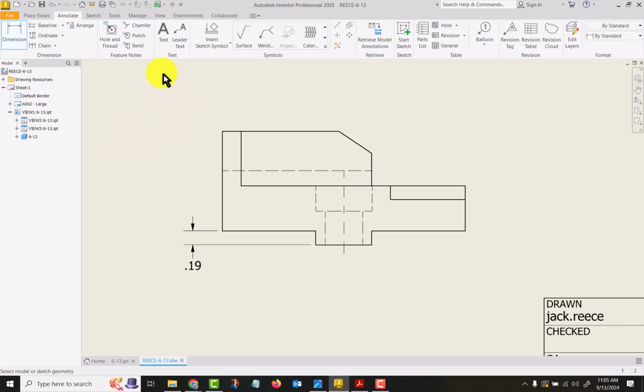And so now I want to put my next dimension in. So I'm going to go back to this line and come to this line and pull out and align those up and then snap it. And now I want to do an overall. And you notice you do get corner snaps. And now look, the spacing is okay on that.